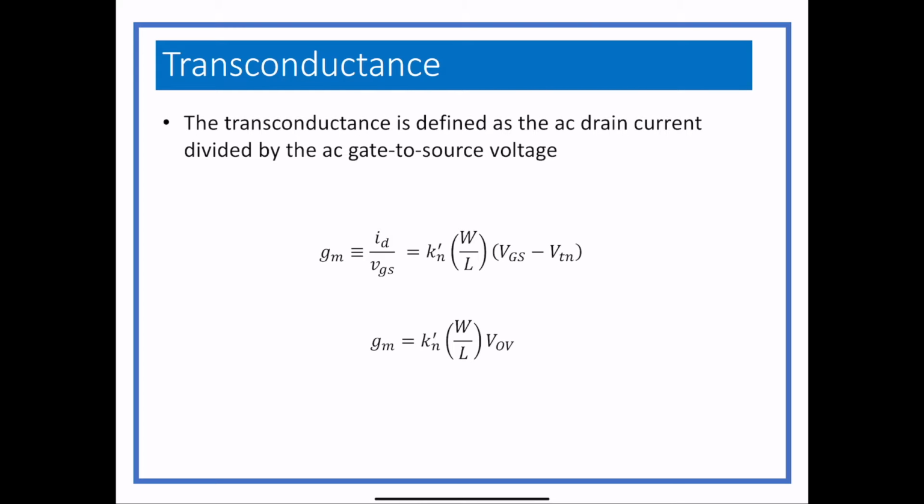But this is what the DC values in the circuit are used for, finding the transconductance, because that goes straight into the AC model. So the DC drain current, whatever that might be, is actually what has an effect on this value, gm.